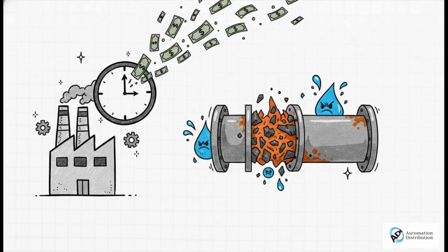It causes corrosion, it creates pipe scale that actually breaks loose, travels right through your system and blocks your air passageways. And what does that lead to? Massive, system-wide pressure drops and severely degraded machine performance across your entire facility. This damage is wide-ranging and it's completely cumulative.